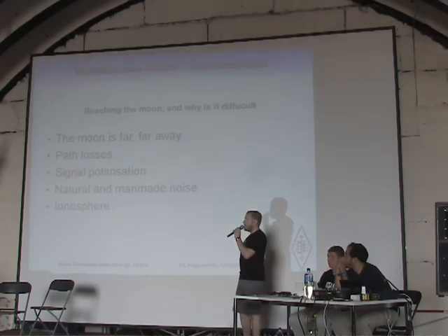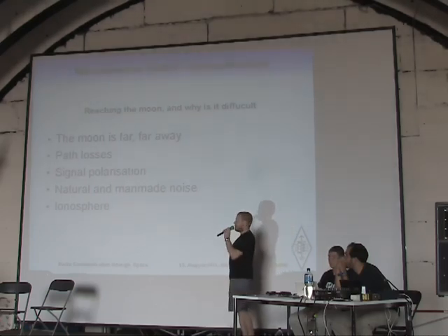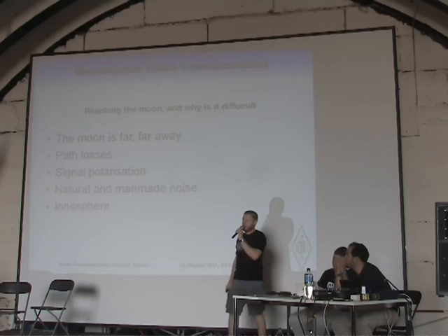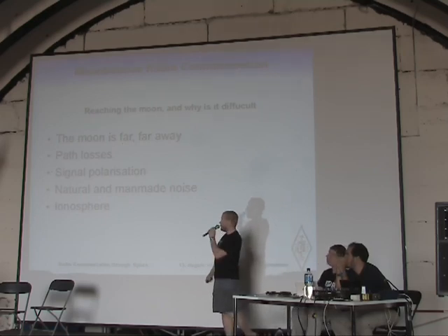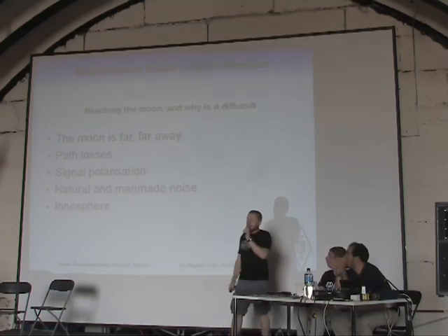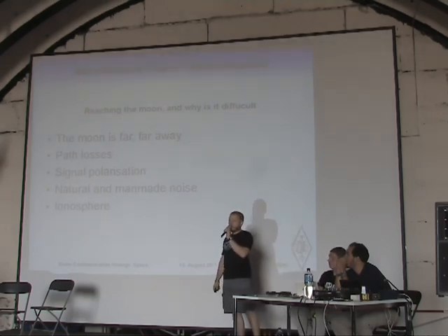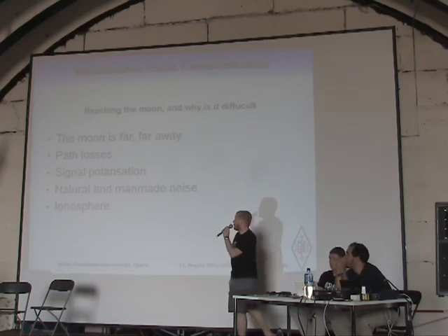So you might not be able to hear a signal because it's rotated 90 degrees, which gives a lot of signal loss in receive. Nothing specific, but you have to know that. On the other hand, it's quite good if you're standing on the North Pole and another guy stands on the equator, you have 90 degrees polarization difference anyway, so that might help as well.